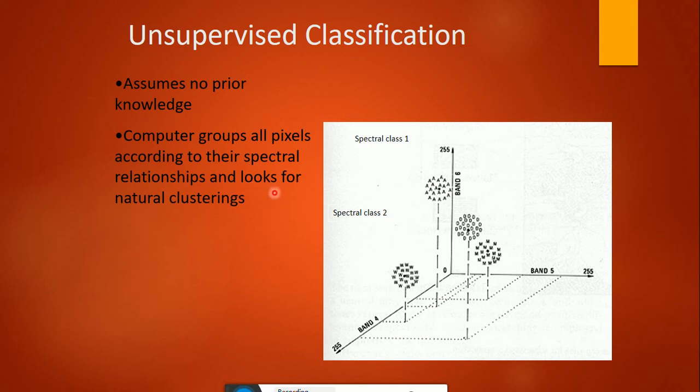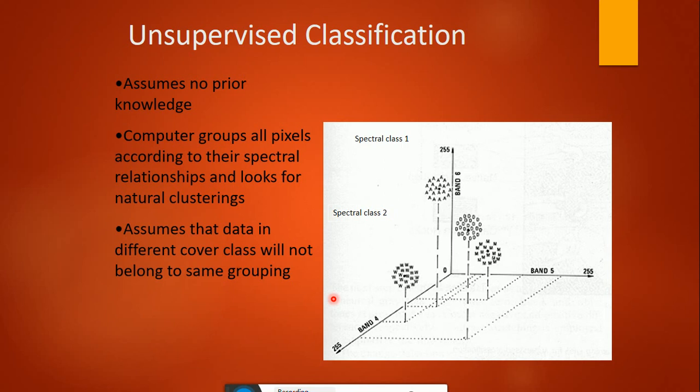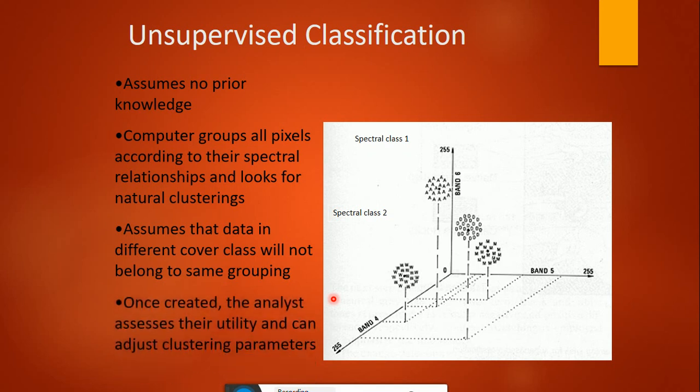Thermal process and properties. A thermal sensor essentially measures the surface temperature and thermal properties of targets. Thermal infrared images generally record broad spectral bands, typically 8 to 14 micrometers for images from aircraft and 10.5 to 12.5 micrometers from satellites.